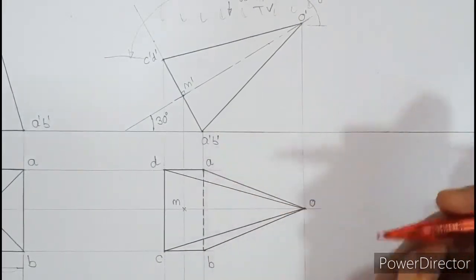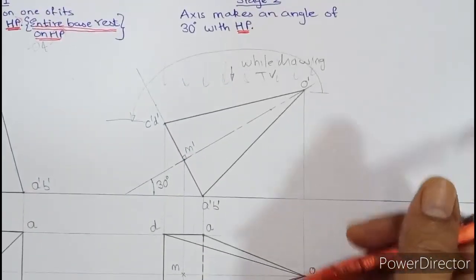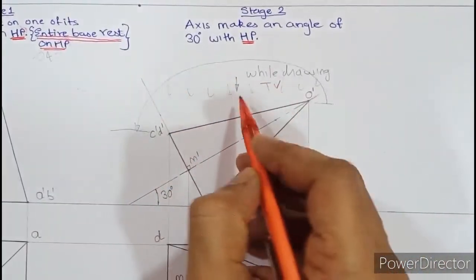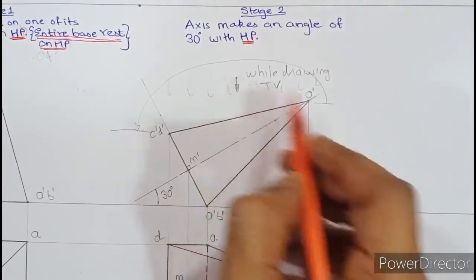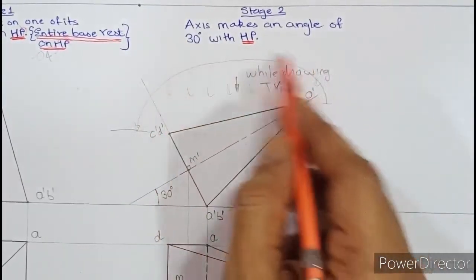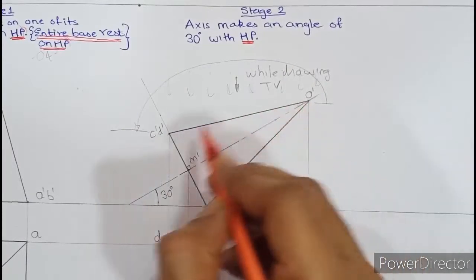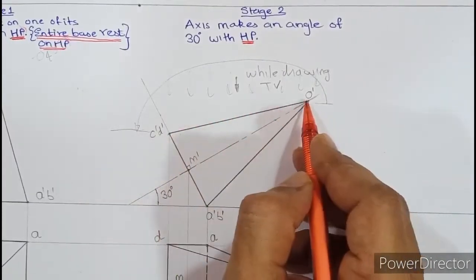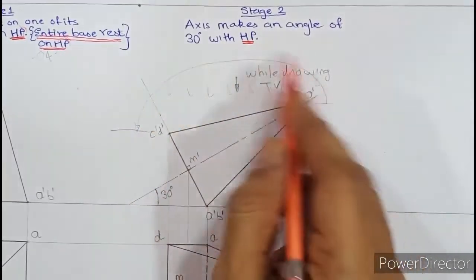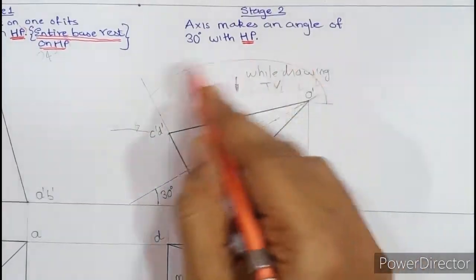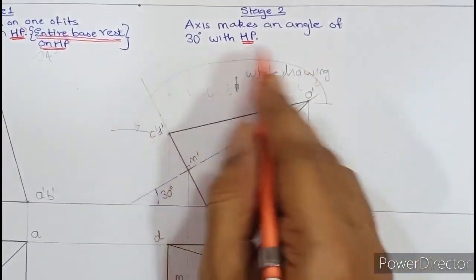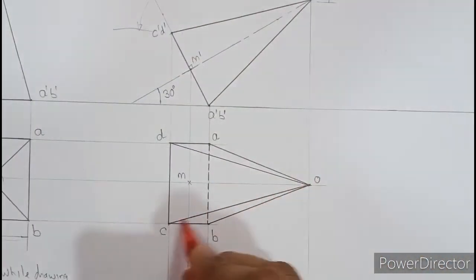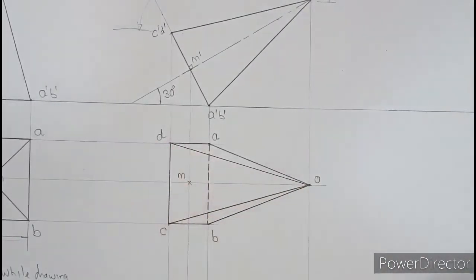So if you don't want rote learning, and by understanding if you want to make out, again look at this diagram. You're looking from the front view, you can see everything within 180, that is your scope. Can you see slant edge OC and OD? That is the question: whether OC and OD lie within 180 or beyond? The answer is within. Because OC and OD lie within, in the top view OC and OD can be seen. It is as simple as that.